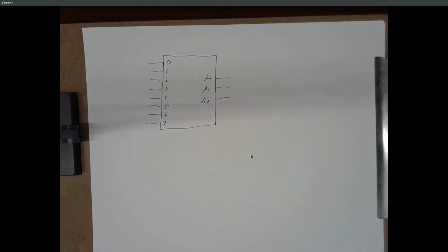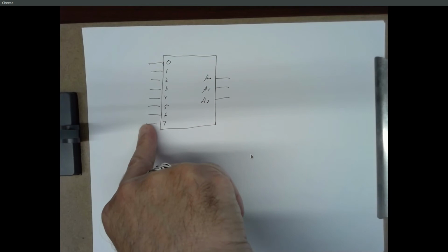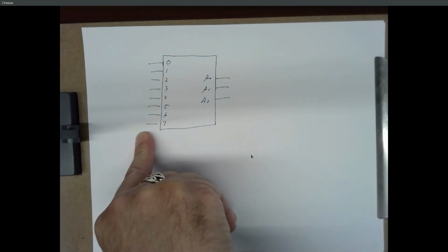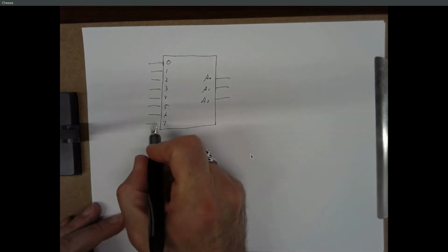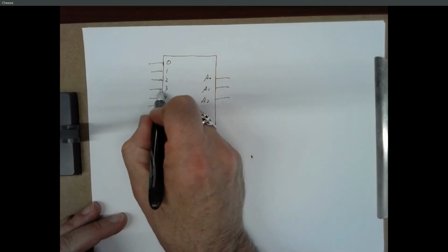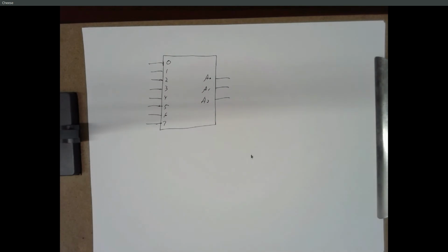But what event should we pay attention to? Suppose multiple things happen. There's a keyboard press, there's a network packet, and the CPU is getting really hot. Right? Probably we want to respond to the CPU getting really hot first. That's the higher priority event. We want to turn the fan on, make it go a little faster. So the idea is if you have multiple inputs that might require your attention, we can prioritize these and say, let me know what the highest priority event is.